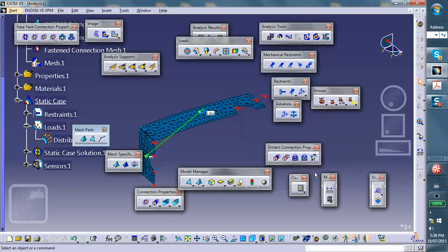Finally, let's see, what did I want to show you here? Yeah, that's pretty much it. So you found out that if you join surfaces, the thickness will end up being the same. If you don't join them, then somehow you have to ask them to talk to each other, and this was the process. In the first run, I made an edge-to-edge connection and made that fasten. Then I showed you a face-to-face connection, the horizontal sheet and the vertical sheet connection, and then fastened them.